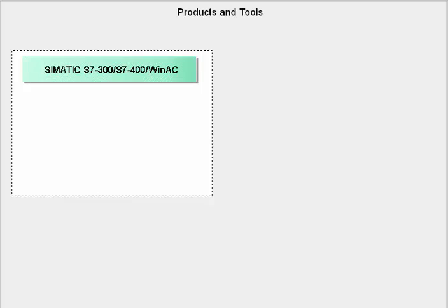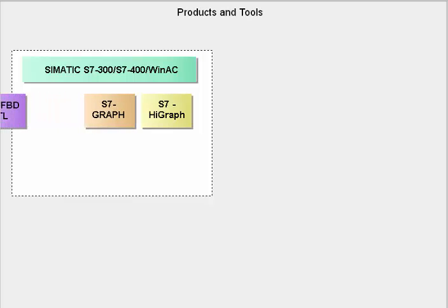Process diagnostics in Simatic includes different additional products that are integrated by TIA into the individual overall solution via optimum system interfaces. These then provide a consistent interaction between the Simatic languages, the options packages, and the HMI configuration tools. Process diagnostics in S7-300, S7-400 or WinCC systems is embedded in the languages S7 Graph, S7 HiGraph, and ladder, function block diagram or statement list.